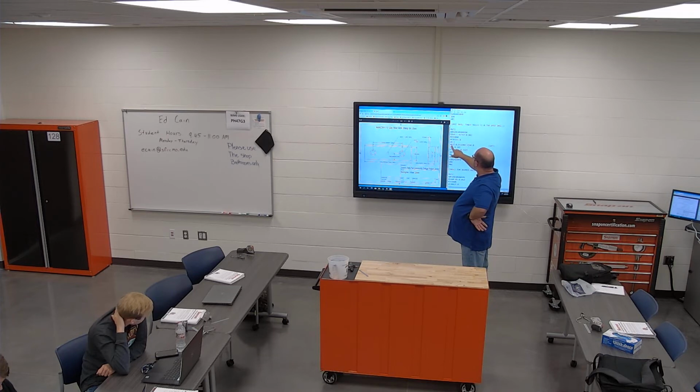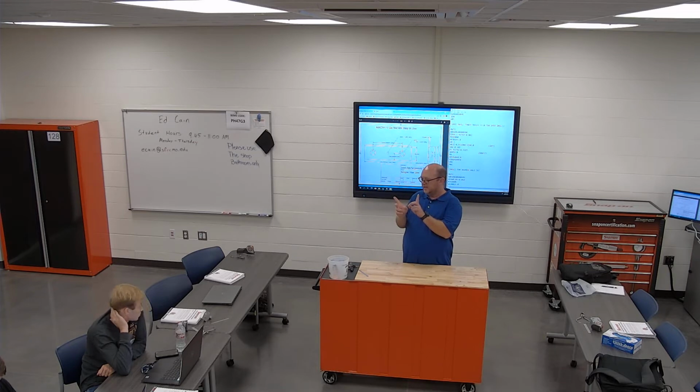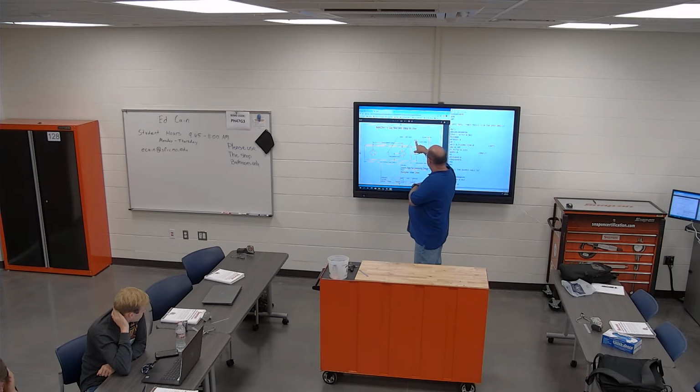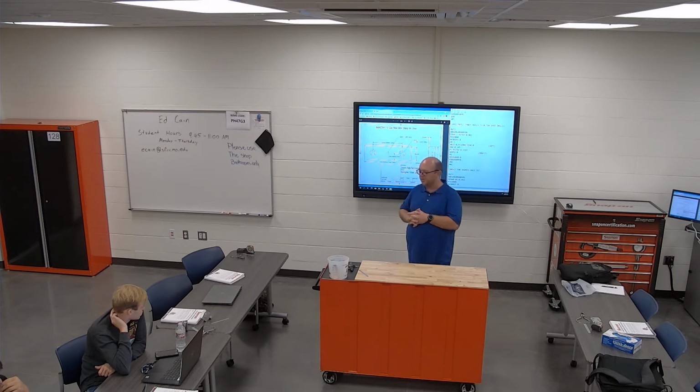Then we do a canned cycle, which is G82. And they went down 532 thousandths. So when you do these holes, you take your spot drill 45 degrees, right? And then you take the diameter of the hole that you want. So the diameter of the hole is finished at 530. You divide by 2, and then you have to add all the material that we took off the top. And that's approximately how much you can go down.